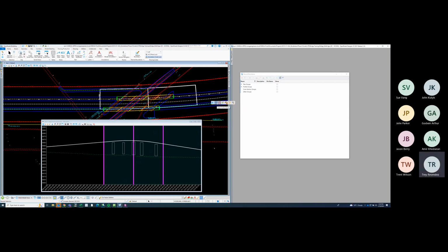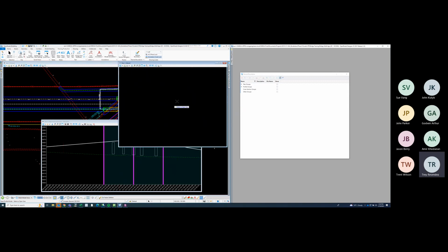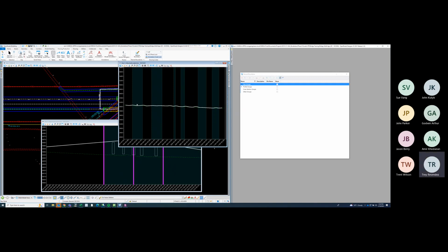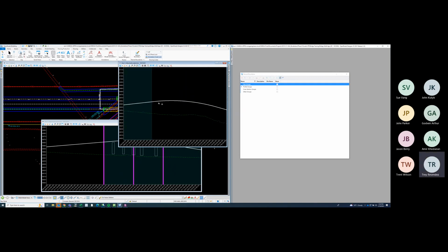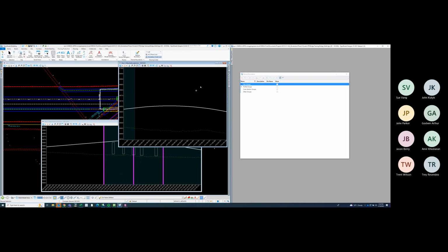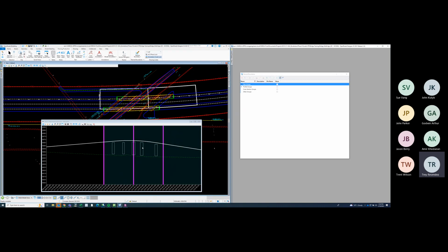Click on this, open profile model, and then you'll open up a view, say 3. You'll put it in here. Then you find your location of the bridge, wherever it is. Let's say it's at 764. Then you can start drawing your bridge. So that's something that I would get familiar with if I was doing it this way.